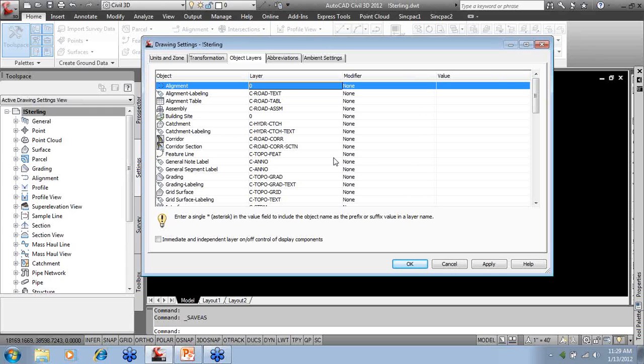When you first go to Civil 3D, your goal and your habit, a better word, what you're used to, is to run everything by layer. Yes, there are some advantages, but I promise the more you work with Civil 3D, the more you will control everything by styles. So, take it from me, styles are going to drive Civil 3D. You can also use layers, but styles are going to be the most important first of all here.